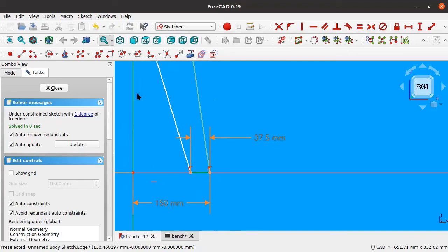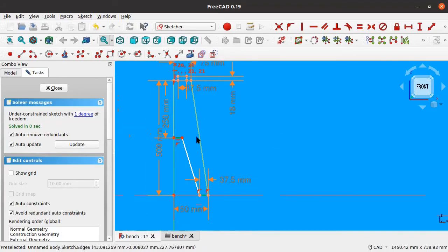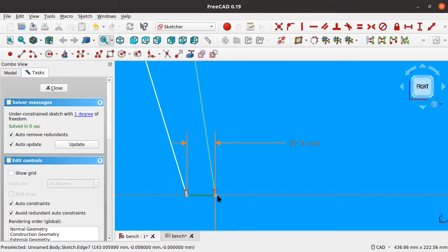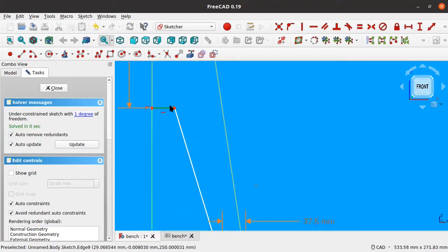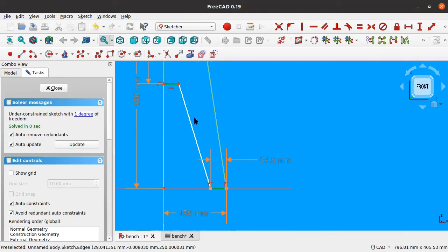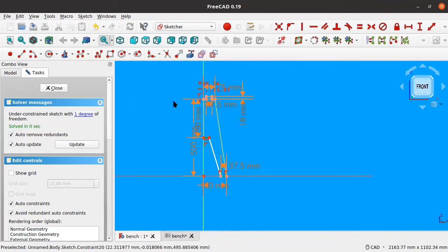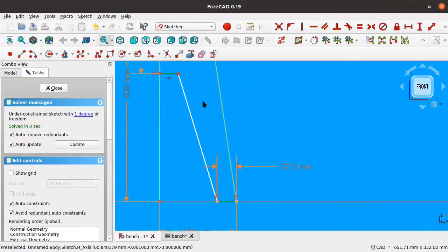And here, in order to reach the right angle so that I can get a bit more thickness on the top and a bit thinner structure here on the end. The challenge is also to have enough surface so that the bench doesn't wiggle on the floor, that it sits nicely on the floor, and the legs do not break. So I have to find the right proportion over here. And 1/8 of the diameter of the seat surface seemed to be a nice choice.